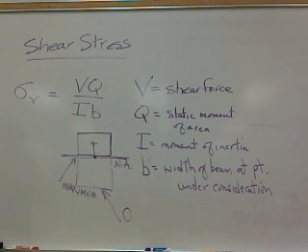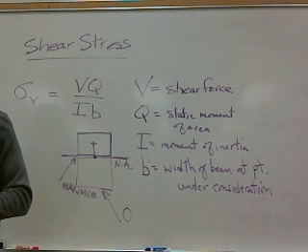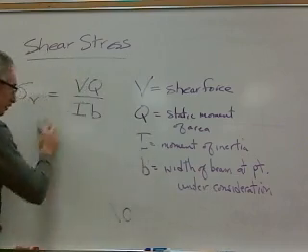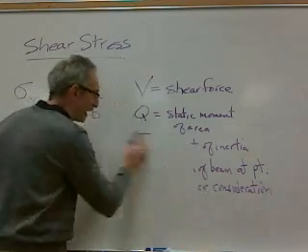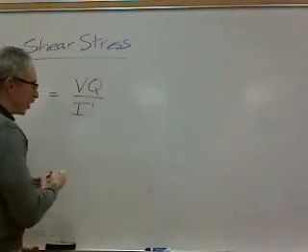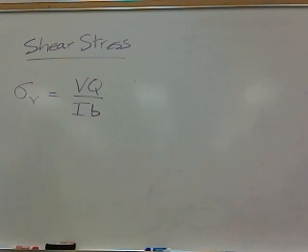Okay, so wherever you're calculating shear stress, look at the area outside of that point. Then take that area and multiply it by the distance from the neutral axis to the centroid of that area, okay? And again, it sounds harder than it actually is. So, let's show you this. Again, one thing I'd stress when calculating this particular formula is, watch your units. It won't be as tricky as it was with bending stress sometimes.